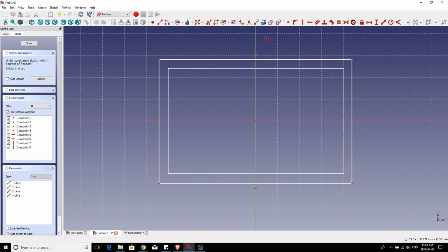So I'm going to click on that, and now as I'm moving over, see how it's highlighting? I want to make use of the 2 points and the line right here to create a constraint for my outer walls. Now you'll see how we're going to do that in a moment. For now, I'm just going to select that. It's going to turn purple, which means that that information is now accessible in my current sketch, even though it's part of the other sketch that I worked on.